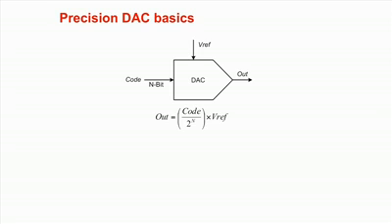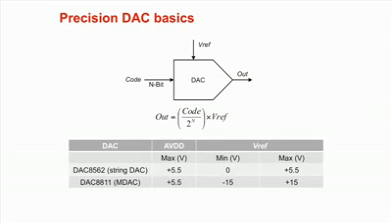For a typical DAC, you need an extremely stable DC voltage reference. However, in some applications such as signal attenuator, where the attenuation is controlled by the digital code, it is useful to have a variable reference. Now, this is where MDACs differentiate themselves. The reference of an MDAC can vary so that it can be substantially greater than the supply voltage itself.